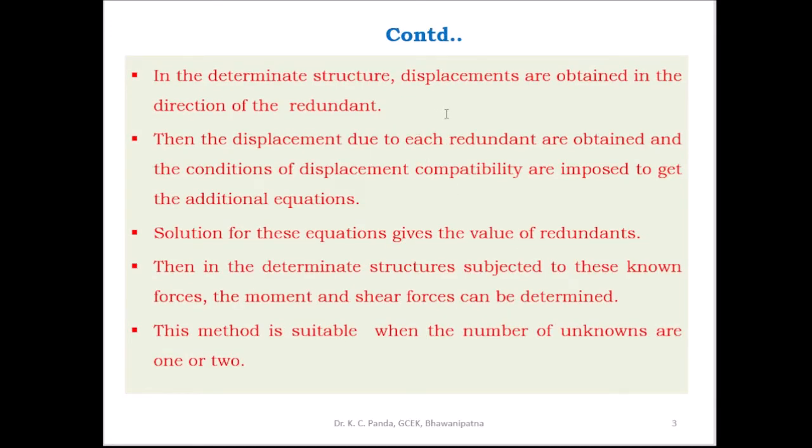Then in the determinate structure, the displacements are obtained in the direction of the redundant. Then the displacement due to each redundant is obtained and the conditions of displacement compatibility are imposed to get the additional equations.